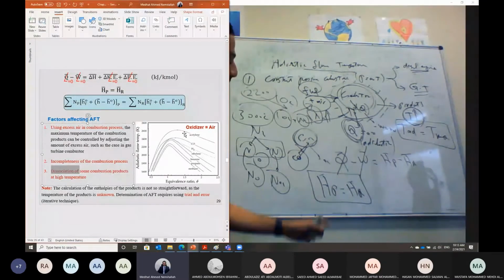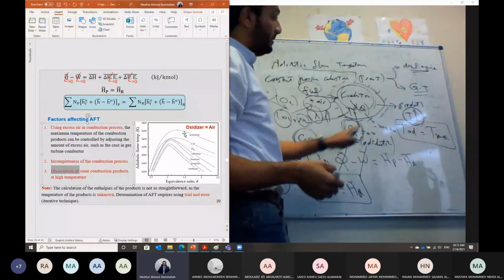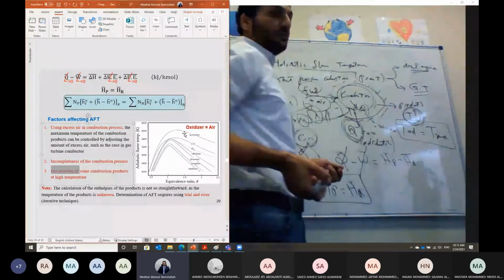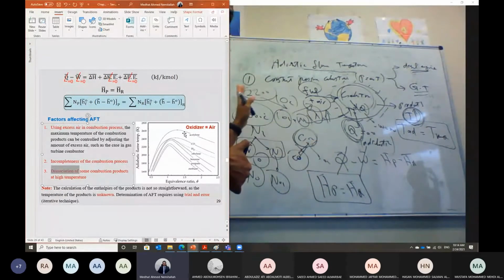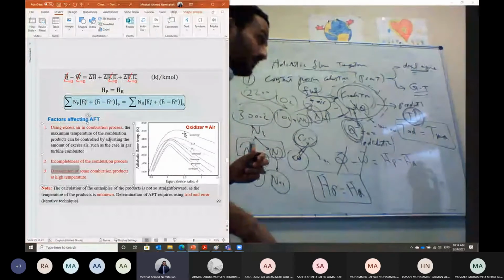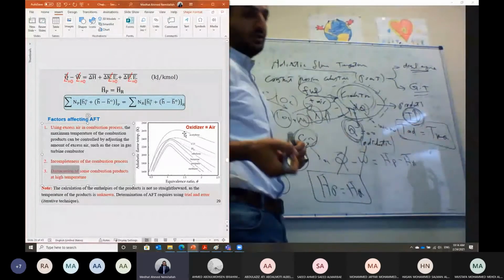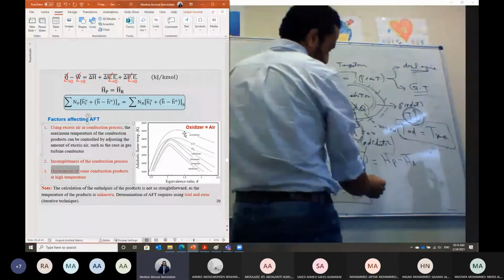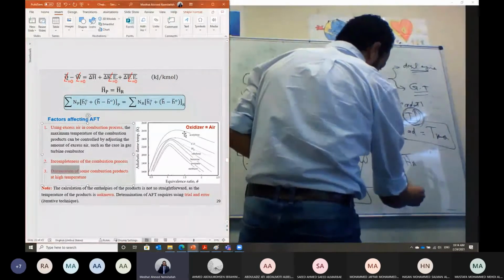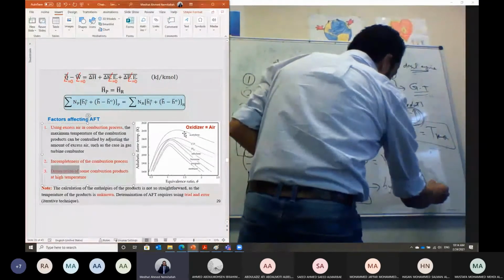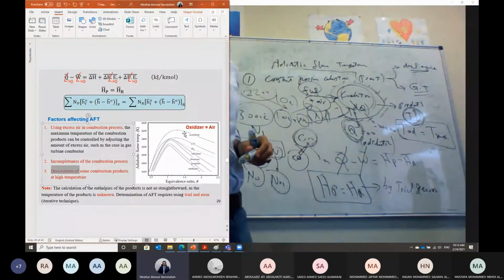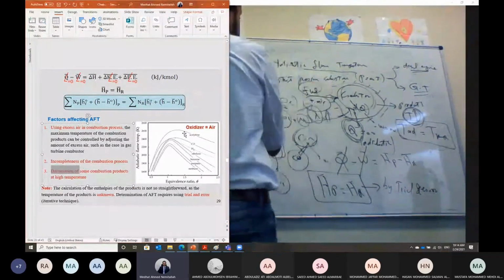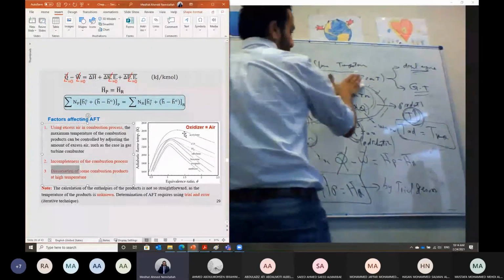But usually, guys, in order to calculate the enthalpy of product, we have to have the temperature of the product. Then we can calculate delta H. Enthalpy of the product gases is enthalpy of formation plus delta H. So I need this temperature to go to the table and then get delta H. But actually, in this case, we need to calculate this temperature. That means this should be done by trial and error. So the solution here will be done by trial and error, as we can see, inshallah, right now. So this is the first case, guys, when we have constant pressure combustion.